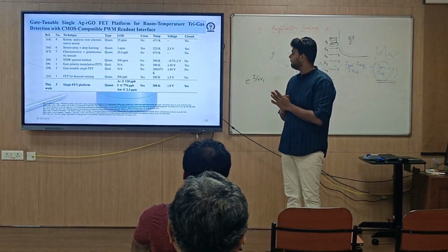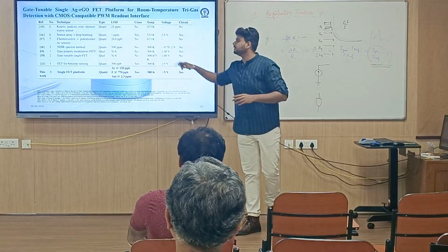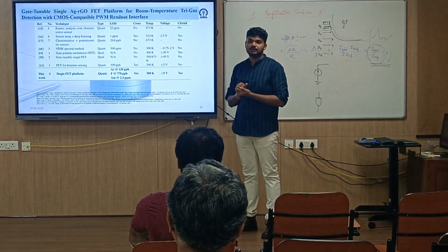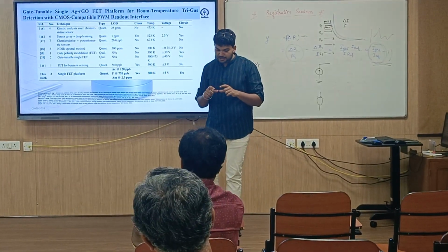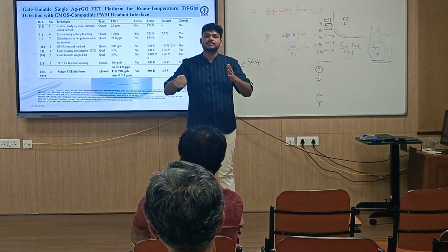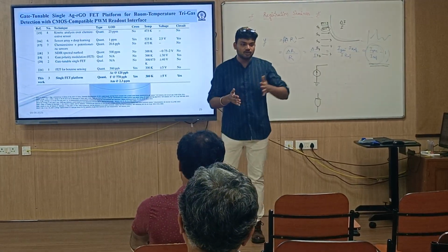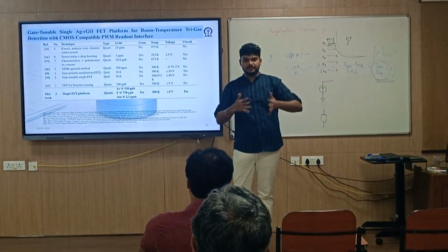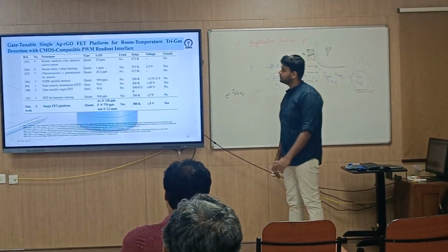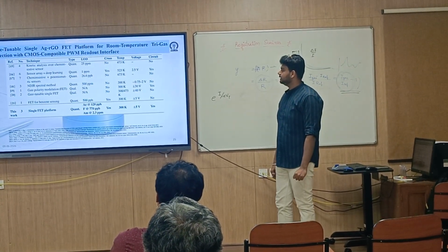So Mayank, just one related question here. This operating voltage that you were saying, plus minus 30 or plus minus 40, these are quite high. So this depends on what? The channel conductivity is very low, so the current is not changing at a lower sweeping range. To put it into a detectable range, that's why they are increasing the VDS. It should probably also be the oxide thickness. Oxide thickness also. Okay. Nice.